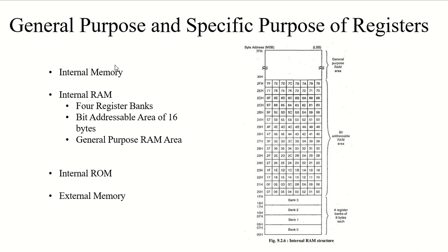But ROM is the read only memory, which is only accessible for reading. Also it does not wash away when you turn off or reset your microcontroller or processor. It is the memory which gets stored on the processor, on the board, right? So this memory is separate from program and data memory, and I'm talking about microprocessor 8051 only. In 8051, we have the internal ROM which is separate from the program and data, and both these memories have the same address ranges.